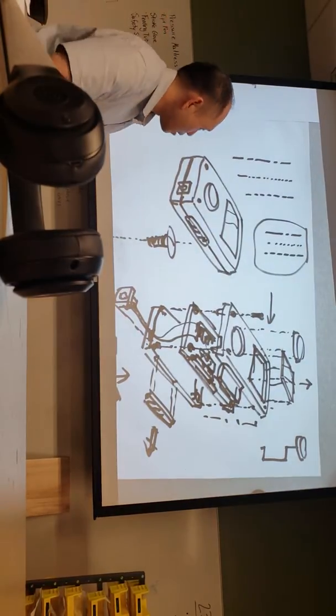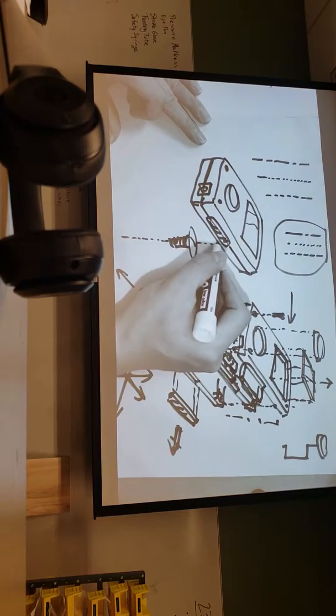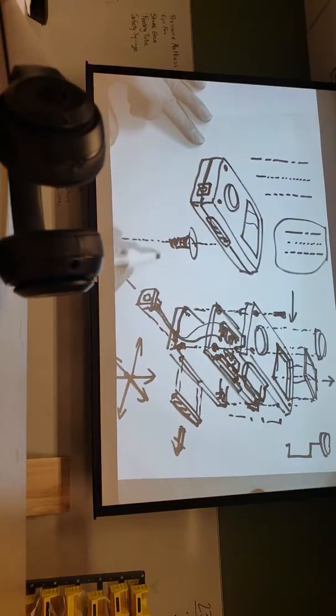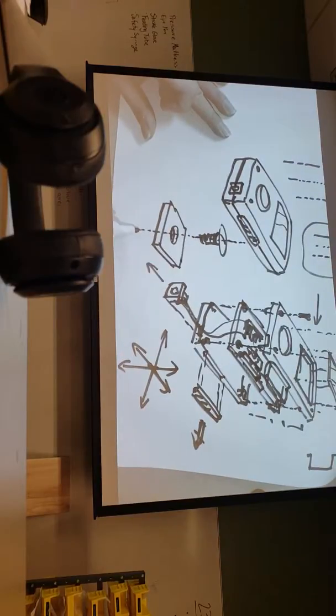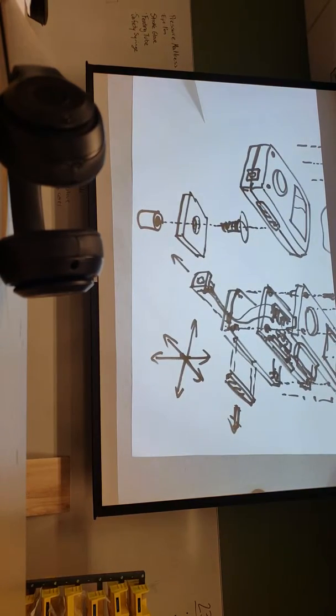Okay, so anyway, that's something to think about. If you have screws, you'll notice that your leader lines are basically the center axis lines for these screws. What's handy is when you have these types of lines, you can have them traced through several layers, so that if it goes through a hole in one layer but ends up in a boss in another layer, that center line helps to line up everything in the exploded view. All right, does that make sense?